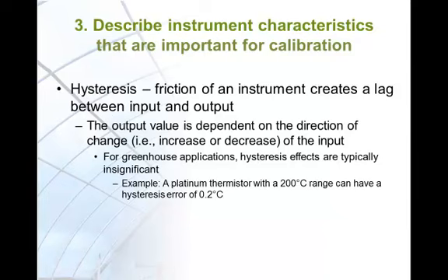I would say plus or minus 1 degree Fahrenheit in the range of 40 to 100 degrees Fahrenheit for air temperature monitoring, and plus or minus 2 degrees Fahrenheit for hot water temperature in the range of 40 to 212 degrees Fahrenheit. The ideally plus or minus 2 degree in the 40 to 212 degree Fahrenheit range is 1/90th or about plus or minus 1%.